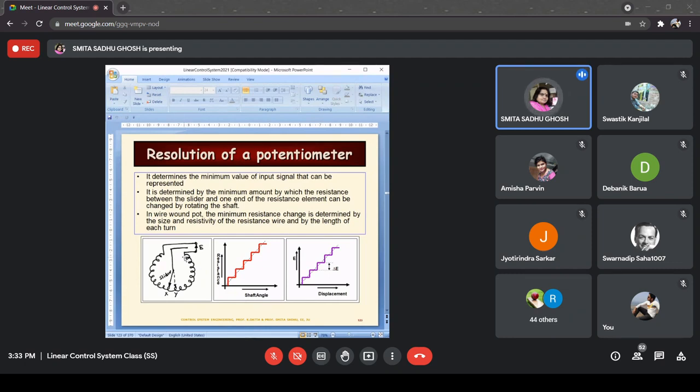So basically, in order to increase the number of turns, making the wires thinner, I shouldn't go beyond a particular point. What else can be done? For example, over here, this is the circular element that you see. Instead of this, I make it larger. You can see the cursor, I hope. I make the element like this from here to there. So this is the size of my circular element. Again, over there I can pack in a larger number of wires, whereas the angular displacement would still remain at 320 degrees, and I make the element larger.